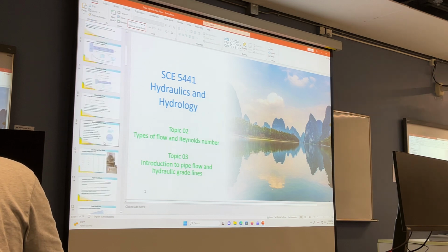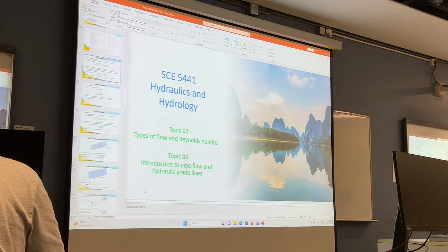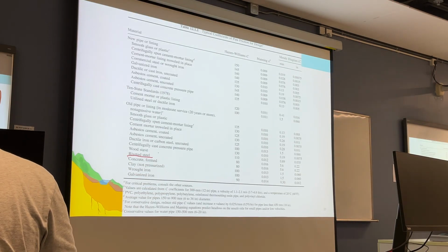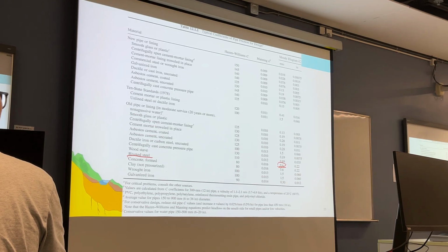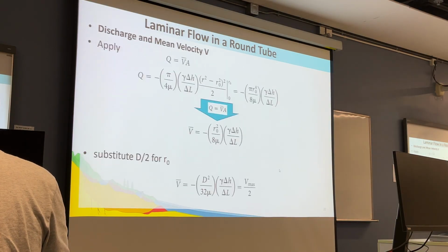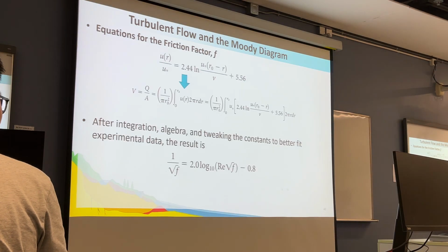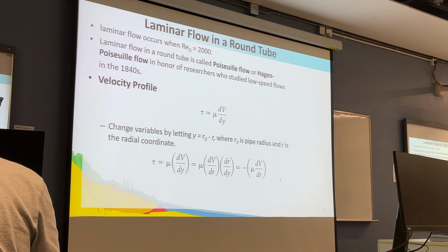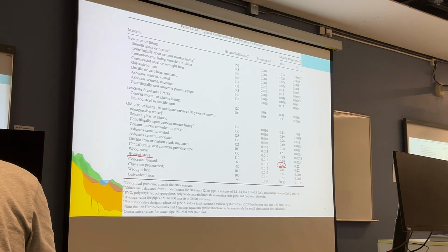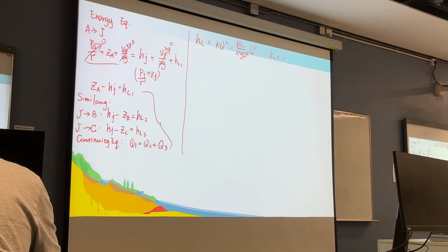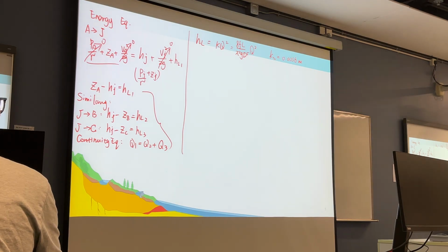Now in the notes, that's riveted steel pipe. I have provided two figures. One figure tells us that the riveted steel pipe is 5.6 mm. The later one gives us only a range, so we take this number, the 5.6 mm number. So the equivalent roughness is 0.0056 meter, in other words.